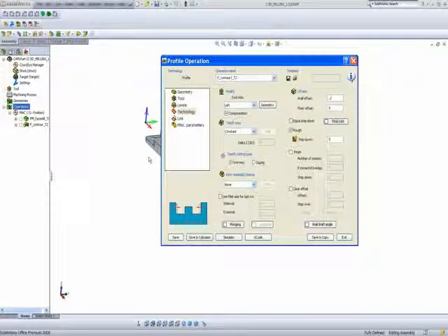Since I'm going down all the way on the outside, I do not need a floor offset. And my finish, I'll also be going down in one step. Now my step down in my rough, I can have at 3mm. And my finish, I'll leave this at 0 since I'm going down all the way to the very bottom.